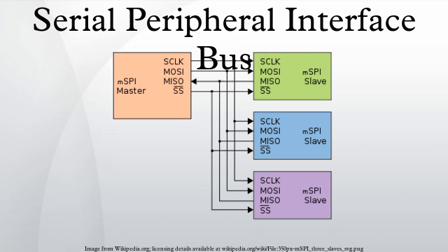SPI is used to talk to a variety of peripherals, such as sensors, temperature, pressure, ADC, touch screens, video game controllers, control devices, audio codecs, digital potentiometers, DAC, camera lenses, Canon EF lens mount, communications, Ethernet, USB, USART, CAN, IEEE 802.15.4, IEEE 802.11, handheld video games, memory, flash and EEPROM, real-time clocks, LCD, sometimes even for managing image data, any MMC or SD card.